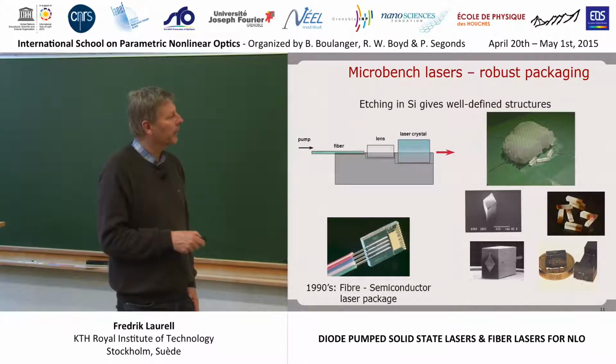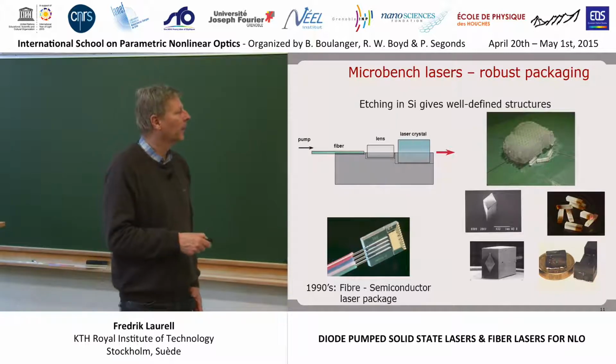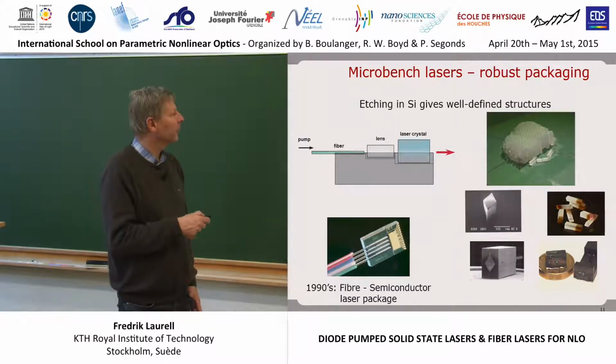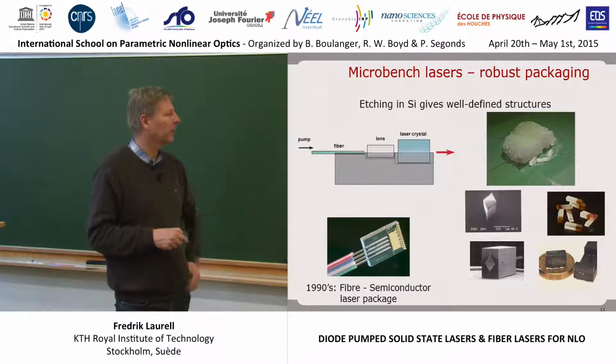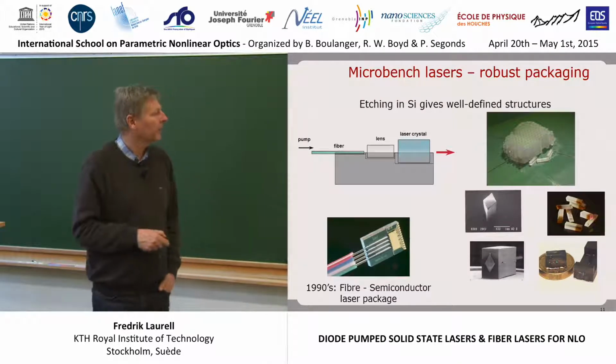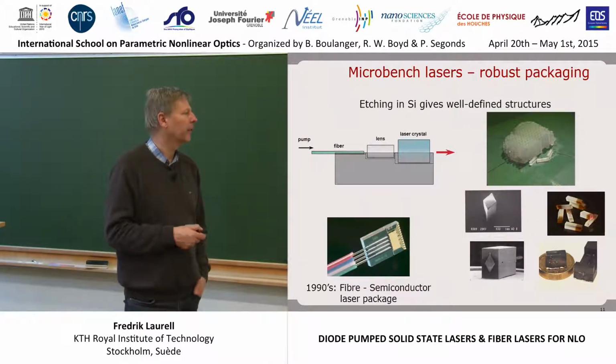You can also integrate the Q switch here. So this is one of these chips here. This is a pure, I think this was the yttrium vanadate chip. And here is a YAG chip integrated with a passive Q switch, a chromium YAG. And such a small laser then, which is just a few millimeters long, can give very intense pulses for marking.